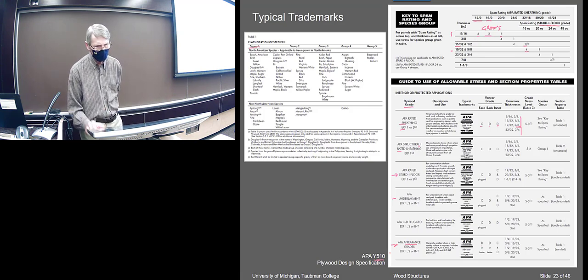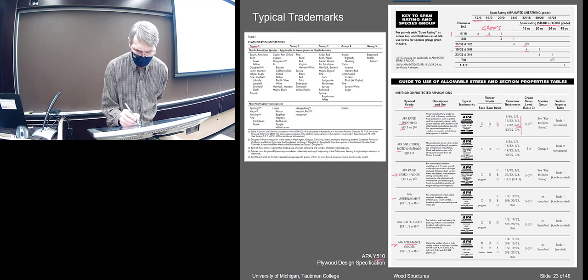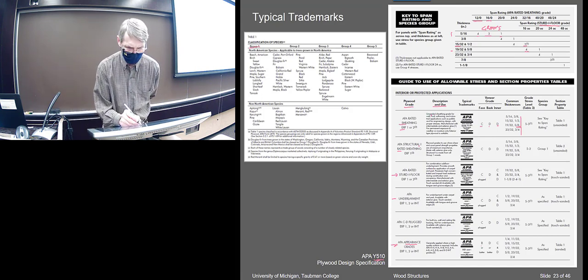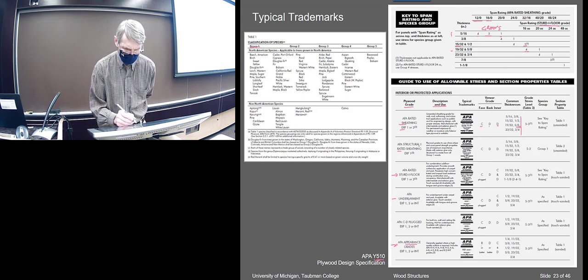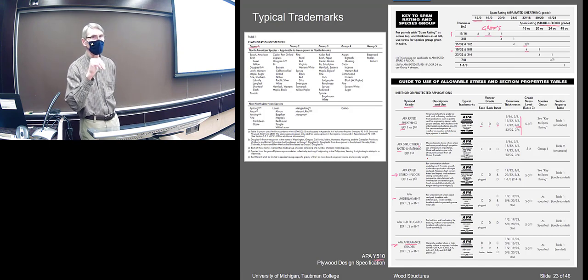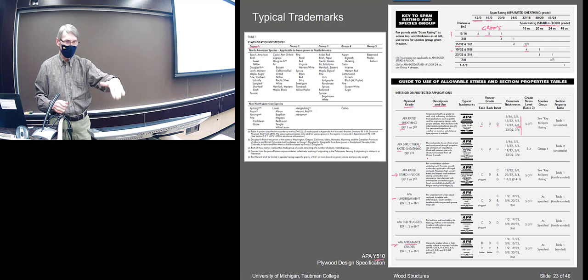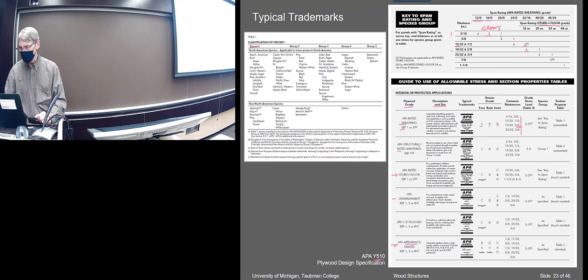Okay, so that, and they give you, if you read this description, it tells you in more detail how they're used, right? I mean, it's sheathing, but here it says it directly, unsanded sheathing, grade for wall, roof, or subflooring. Okay, exactly. Applications, engineering design, exposed to weather, moisture, exterior. Okay, so it gives you all the details. So if you're going through trying to specify something, you'd have to look through that a little more carefully to see which one's really matching up with what your application is.